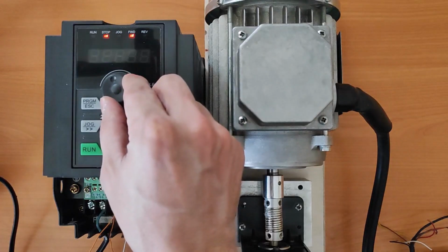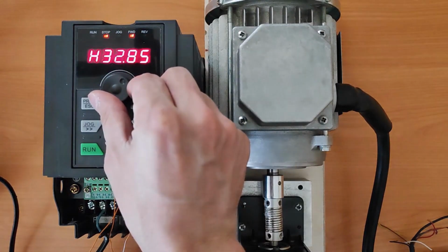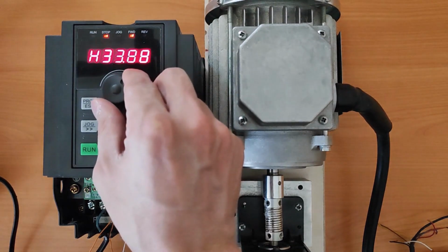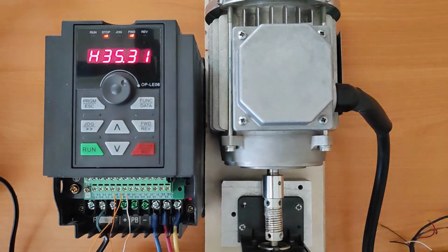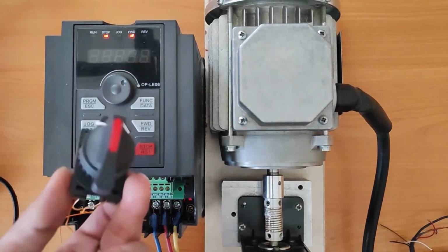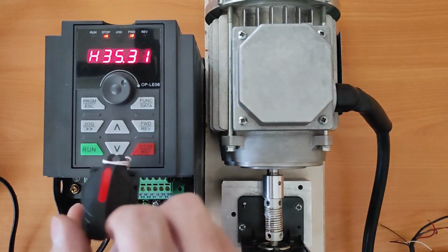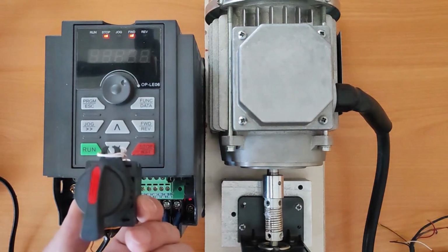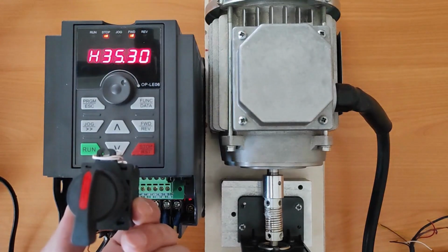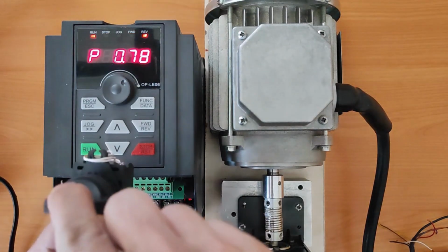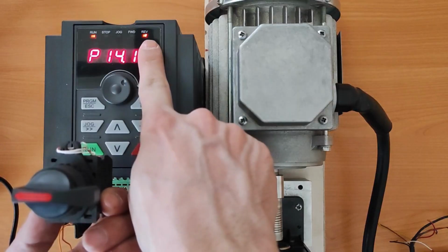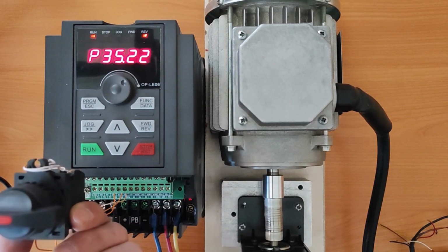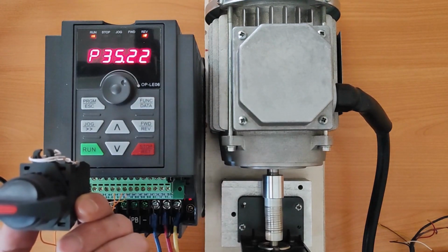You can see that now when I adjust the volume, the current frequency output value of my inverter changes. For this example, I'll set it to, say, 35. Now here I have a two-position switch where I use one position for terminal S1, which means the forward direction, and the other position for terminal S2, which is the reverse direction. Now I activate one of the positions. You can see that the inverter starts running in the reverse direction. The inverter is running and my electric motor is operating in reverse. It starts working at a frequency of 35 Hz.